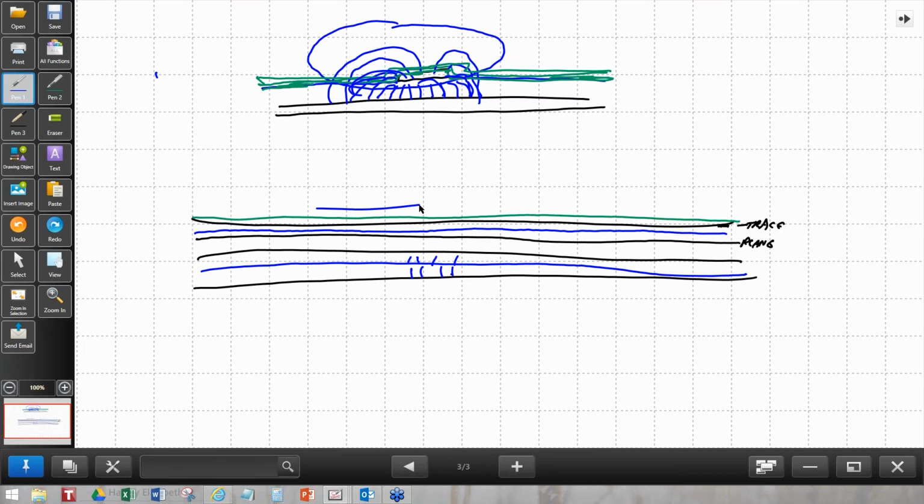So when you make a via, your decision on whether or not to tent it has to include various things like, is this on the surface? Is this a high-speed signal? If so, whether or not you tent it with solder mask will make a difference.